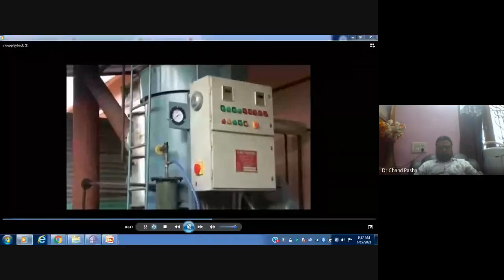Close all the doors and ventilators and switch on the blower fan. Bring a uniform temperature in the tunnel between 45 to 48 degrees Celsius. Now slightly open the fresh air damper and maintain the temperature in the range of 48 to 52 Celsius in the compost for 48 hours for pre-pasteurization conditioning. Now raise the compost temperature to 59 to 60 Celsius by manipulating the opening of the damper or by injecting steam through a boiler. Keep the compost at this temperature for 4 to 6 hours.